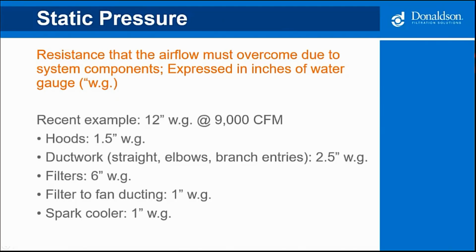Every time I look at a collector, it's got maybe a half inch or 1 when I start it up, and it operates around 2 or 3. Why are you putting so much? That is an upset condition. Let's say that third shift comes in, they elect to turn the compressed air off, or the compressor goes down. Now we're putting all of that weld fume into the collector. It says it's reverse pulsing, but there's no compressed air. We're not knocking down the DP. So I still have to keep my air volume at the hoods, so I have to allow for that upset condition.